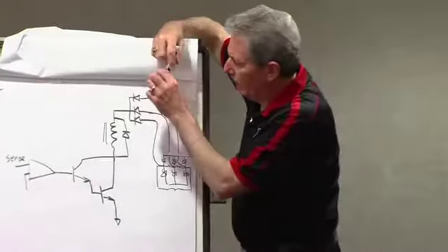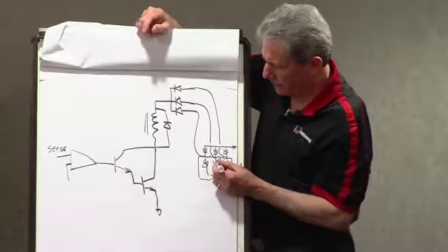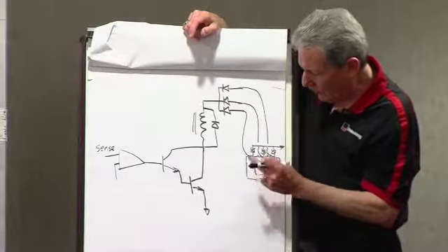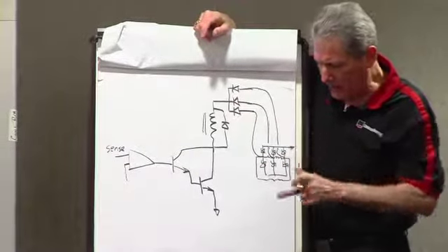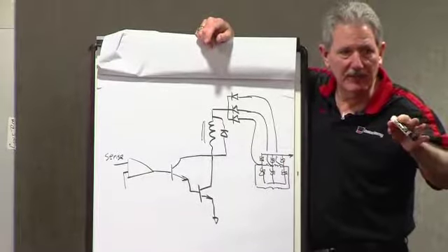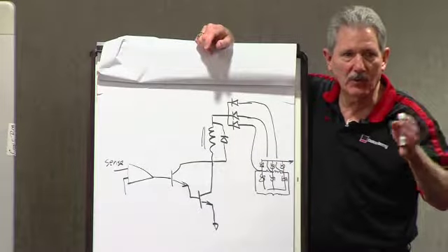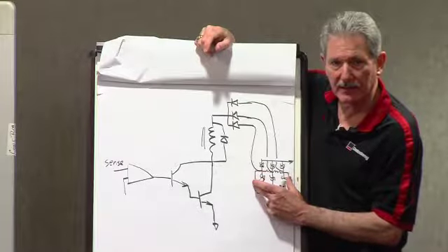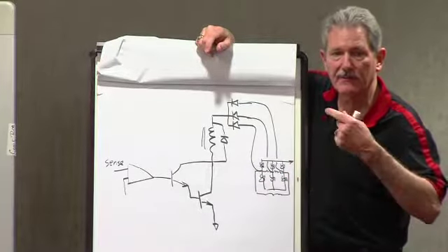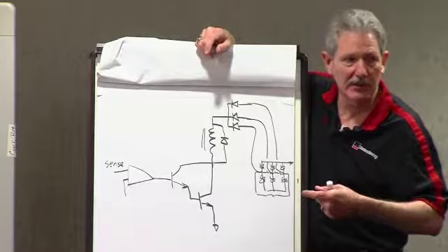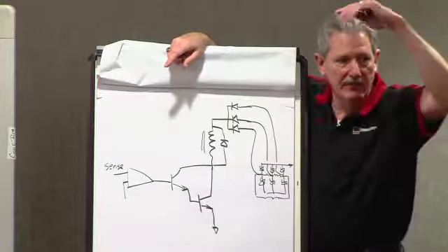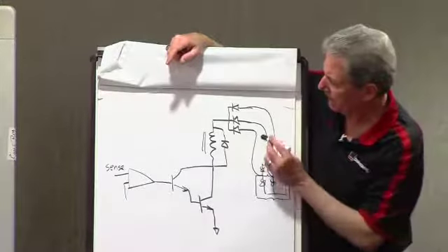The current for the field is magnetically coupled to the stator. When the alternator begins to rotate, and I'm going to assume that all of you have been through the Alternator 101, the stator cuts the flux of the rotor as it goes through, and it converts that into current. The current pushes into a load to get the voltage.